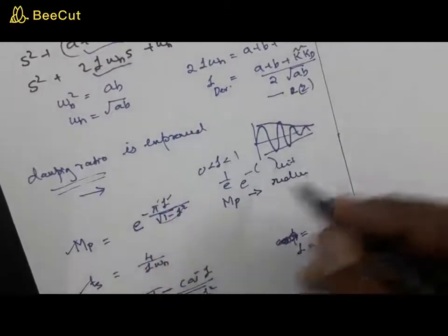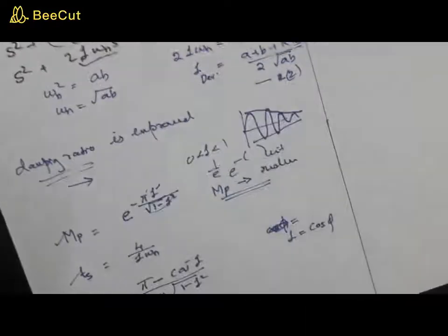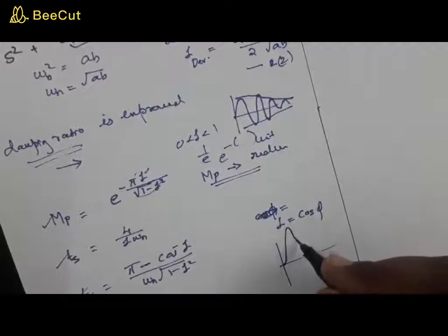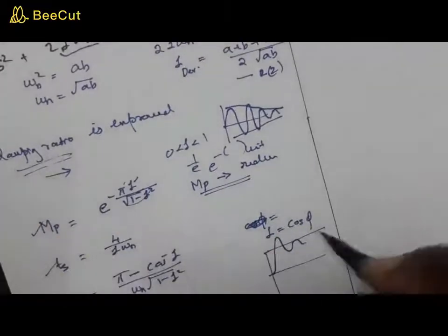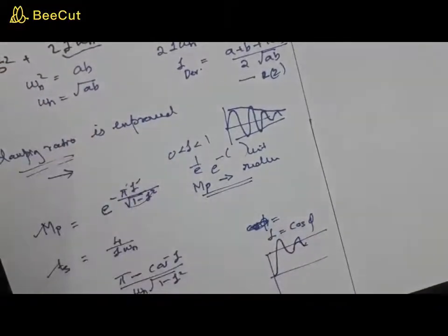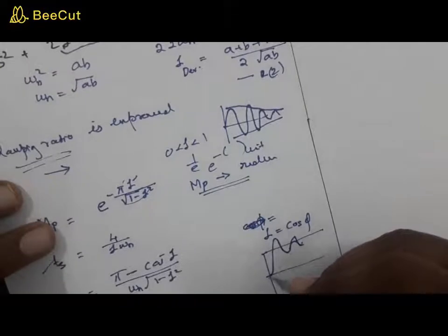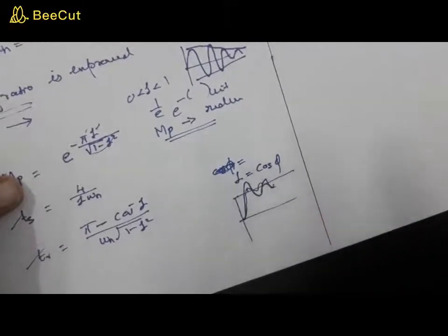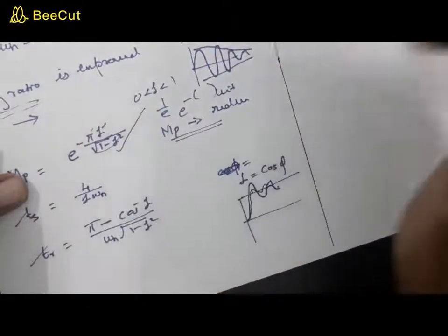The maximum overshoot, the meaning is, say suppose you have a system like this whose output response is this. If you connect a derivative control, this maximum overshoot reduces. That's the meaning. This maximum overshoot reduces. That's number one, and that is an advantage.